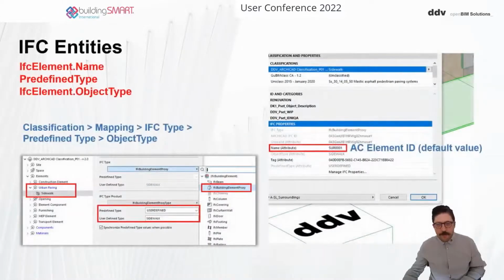And also based on that, of course, when we are creating those objects and we are mapping them into some IFC entities and using a classification system as the keystone to those mappings, here I want to show you one example. Imagine that we are modeling a building, a normal building model in which there are different urban elements, and you know that urban elements are out of the building domain, and for example IFC 2x3 does not cover the urban domain.